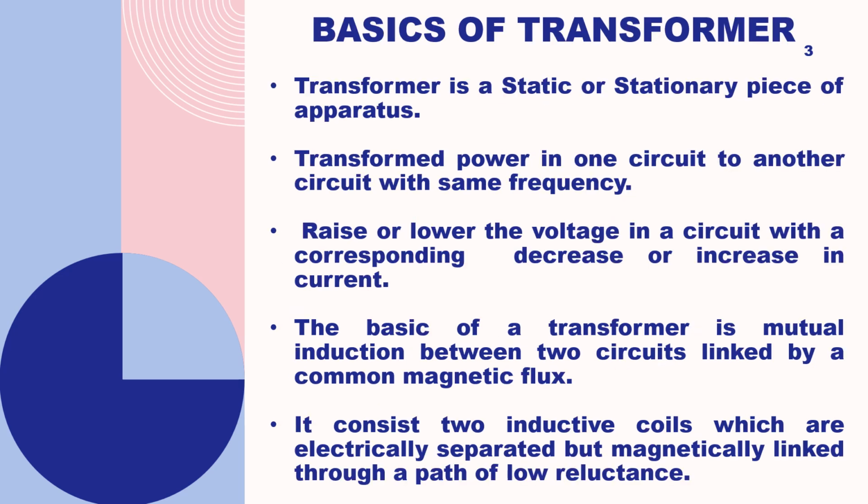The basics of transformers. A transformer is a static or stationary piece of apparatus. It transforms power in one circuit to another circuit with the same frequency. Transformers raise or lower the voltage in a circuit with a corresponding decrease or increase in current. That is, current is inversely proportional to voltage.